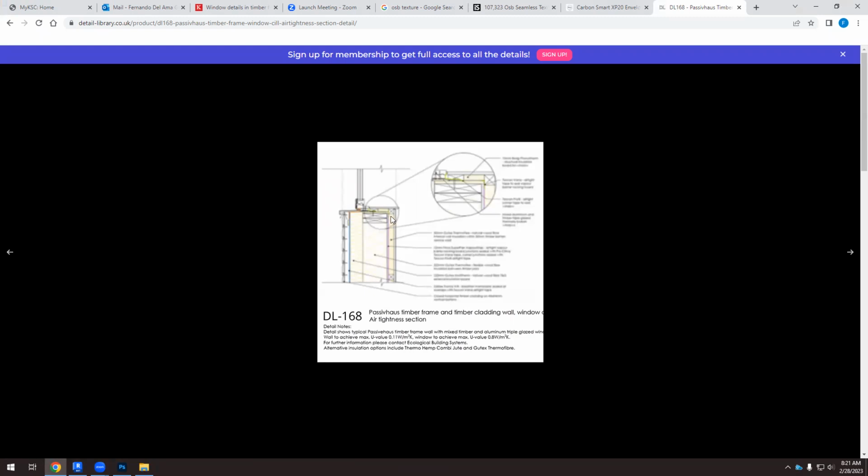But you know that we can't expose the thermal insulation. We need another element. So we need another horizontal element here. Okay, so that's what we're going to do. So we have here the cellulose. Here they have an extra outdoor thermal insulation. We don't have that. We have an extra thermal insulation inside the window. And here they have the exterior siding. And we have to protect the window from the water. Okay, so here you see that they have this element. It's small.